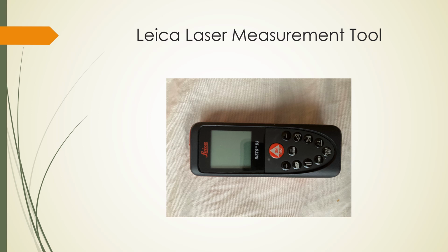Pacing out is not the most accurate system in the world, but I can tell you, having paced hundreds of systems, I pretty much knew the difference between a 10-foot and a 12-foot spacing. I was pretty confident. I couldn't tell you the difference between 9 feet 6 and 10 feet. That was not within my spacing accuracy. But to pace out 10 to 12 feet, I knew what I was doing. And grabbing information through the laser that is accurate enough to give you head spacing is critical. It is absolutely critical because it tells you a great deal about the system design.